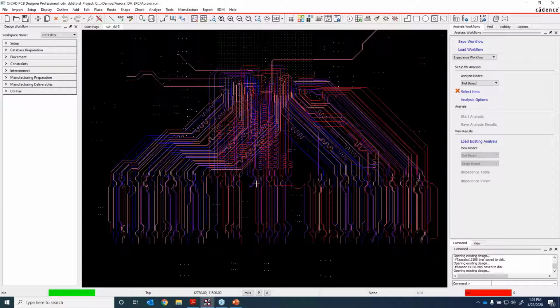It looks at the nets of interest and tracks, from starting point to destination point, the impedance that net presents. All the individual segments, the bends, the turns, the neck downs, the escapes out of pin arrays, will be analyzed for impedance, and it will show you how the impedance changes along that trace route.